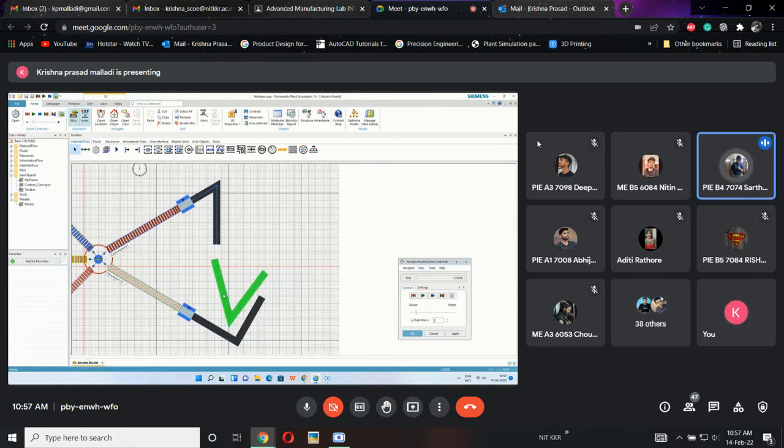Sir, it also depends upon the initial orientation of the conveyor that you define. If it is along the x-axis, then 30 will align with the 30 in the conveyor. But if you define it at an angle, then the angle will be taken as reference and it will be 0. Yes. If you are following an absolute coordinate system, which means you are defining the conveyor in a straight line parallel to the x and y axis, then it will use that x and y. 90 is a reference and it will convert the angle.